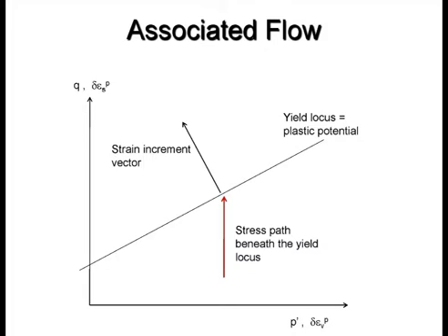That is the reason why yesterday when you ran the thing, first you see a straight line coming up and then you just go up. That is the stress path. You see? Because you are forcing the stress path to go up there. Because the soil is trying to dilate, you're trying to force it back. The only way to do it is to increase the mean effective stress to recompress the soil skeleton back.